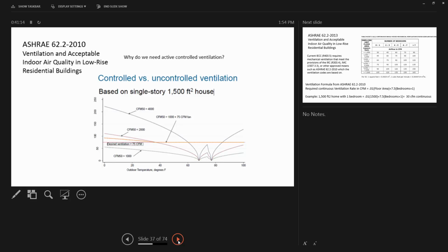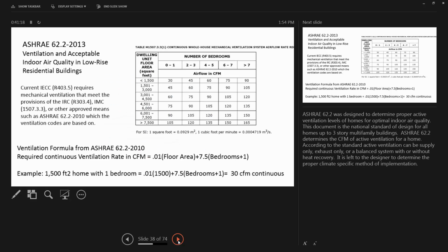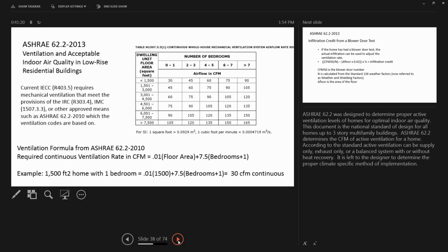We'll get into a lot of the air ventilation requirements, and we don't need to go into that today. So the 62.2 minimum ventilation requirements are also becoming a big part of both residential and commercial codes. And the biggest reason for this, and we'll talk a lot more about it, is that as we start to make buildings tighter and tighter, we get less fresh air into them.